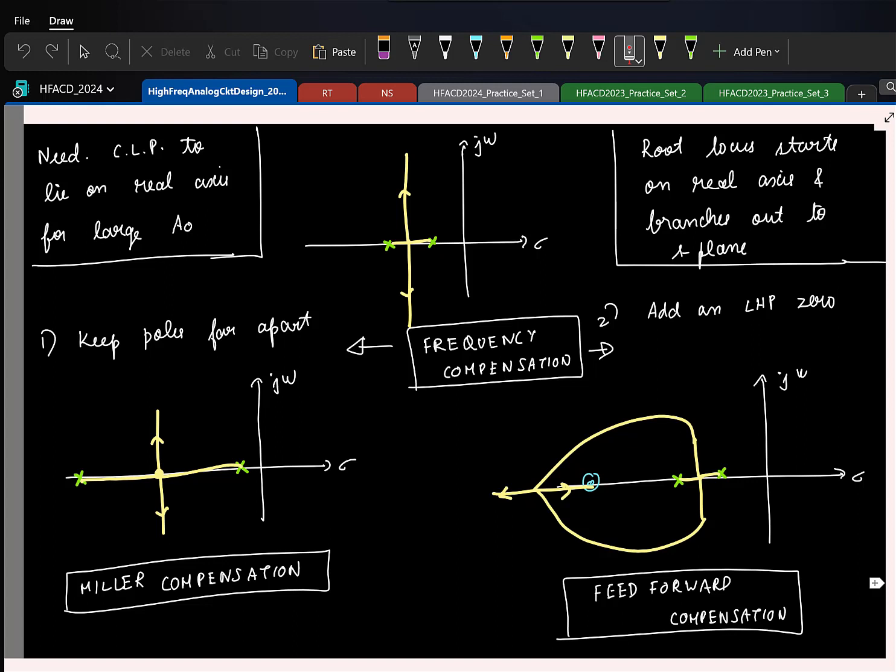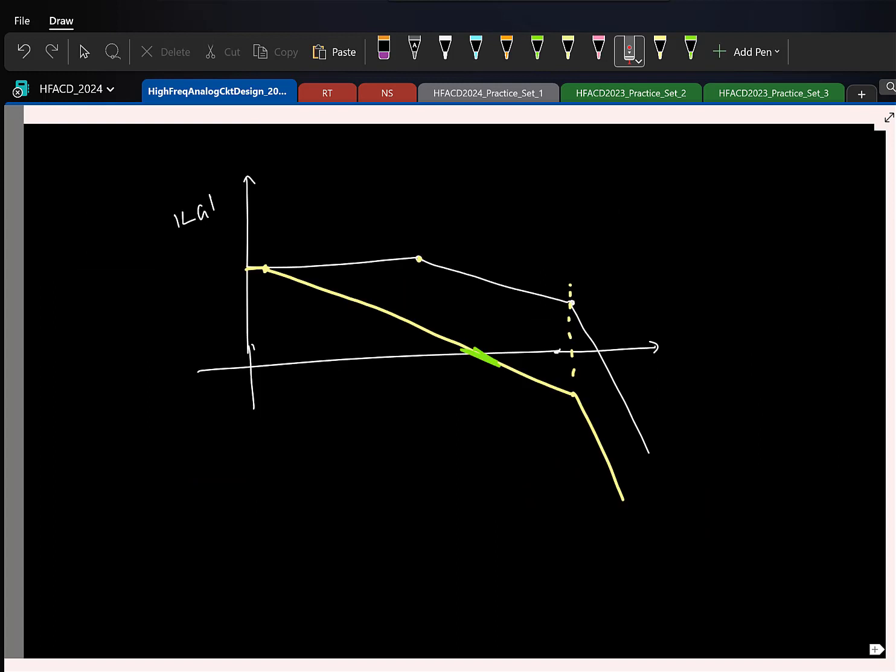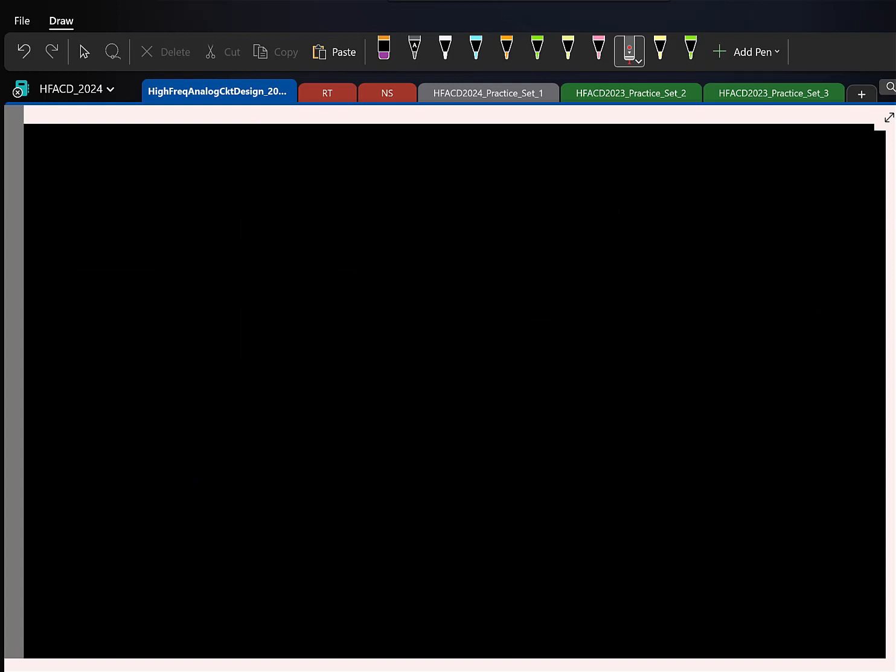Instead of just pushing one of them to a low frequency, you also make sure that the other pole drifts apart. So this will be even better, and as you guys pointed out in the last class, this is something we observed due to the Miller effect, right? And in which context did we see this Miller effect? Yeah, in common source we saw this. So let me first refresh that result.